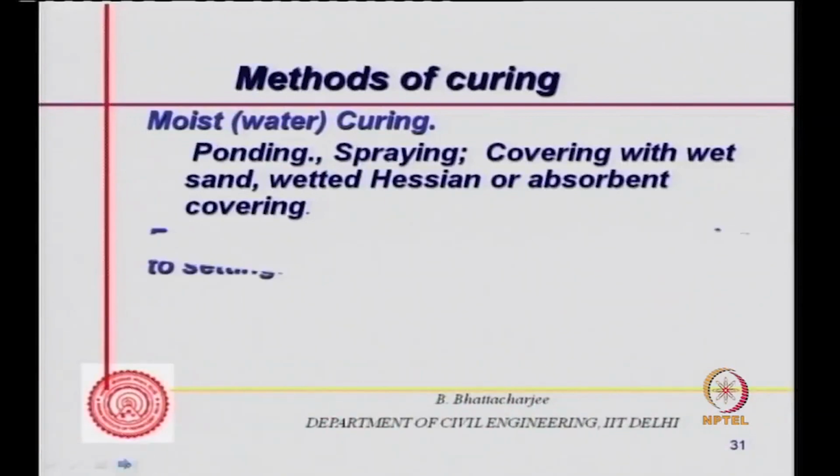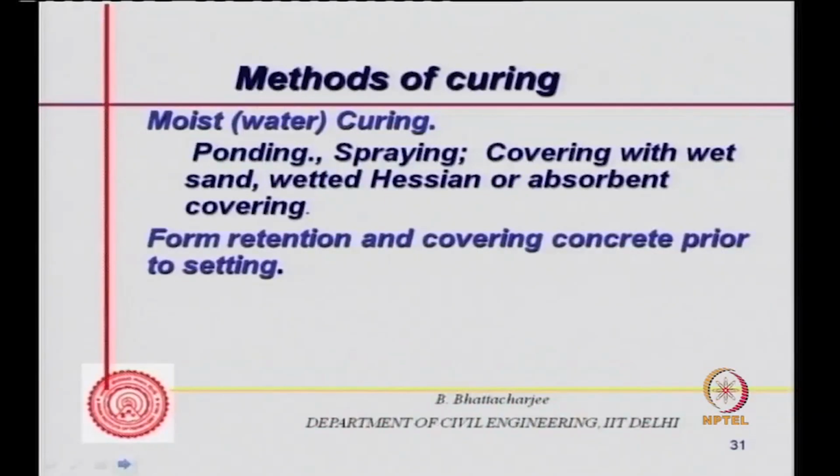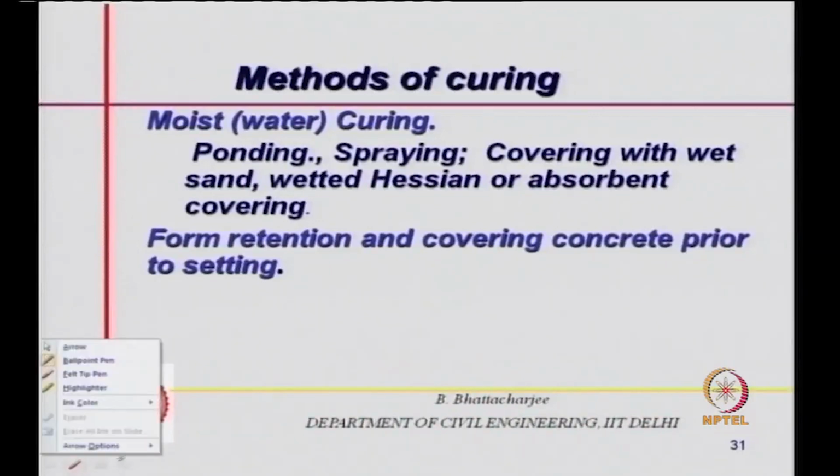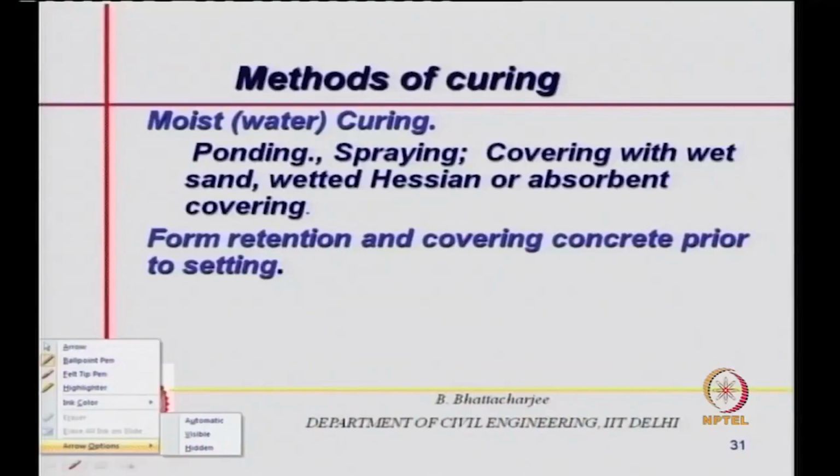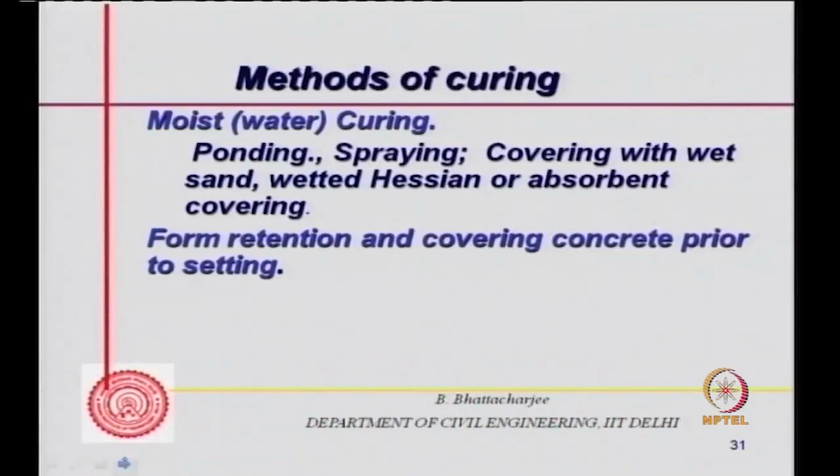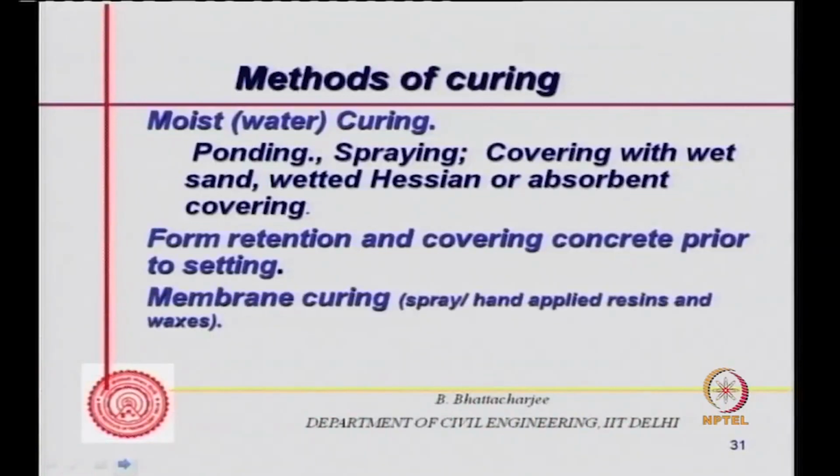Then you have foam retention and covering concrete prior to setting. Of course, you can retain the foam, but that will not be replenishing the water. Or cover the concrete prior to full setting or even after that. So water actually will not go away, but at the same time, it will not replenish the water.